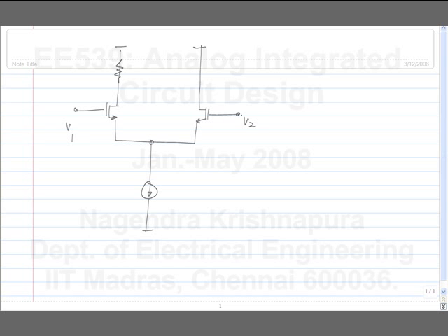Now, if you draw it this way, the symmetry between V1 and V2 is very clear as far as the MOS transistors are concerned. So once you have this, the natural thing is, it looks very much the same, so can I put a load resistance here also? Because it looks exactly the same. So we don't know what may happen. We will make it fully symmetric. That's one of the possibilities. We don't have to do it, but that's one thing that could potentially be done.